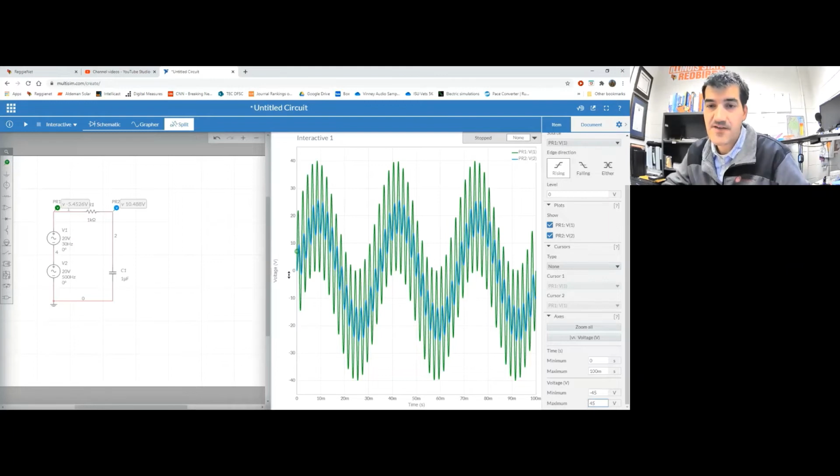What we're trying to eliminate is this really fast up and down, up, down. And all I really want is this slower oscillation up and down like that. So I want this frequency in my output, but I don't want this faster frequency, all right? So I just created an RC circuit. I didn't even change these values when I dragged them out, but in your lab, you're going to change these values to design different kinds of RC circuits.